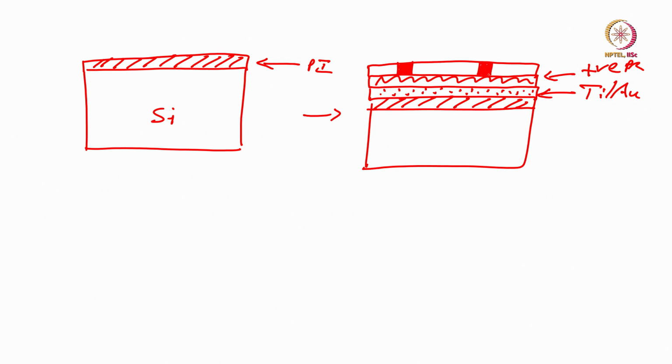And the resolution can also be improved by reducing the size of electrode and having a dense microelectrode array. So this is your bright field mask, and then you have to expose this photoresist using ultraviolet rays.